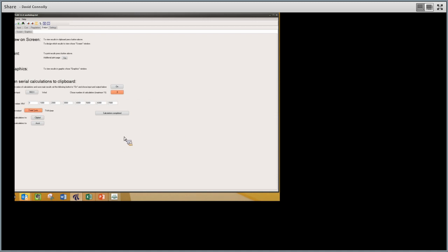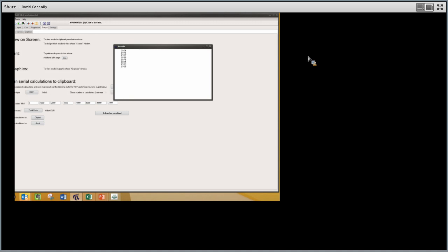I have to then tell EnergyPLAN what result do I want to see for all of these different inputs. So you can click on a variety of different options as the input that you'd like to see the result of. So I'll start by just looking at the total costs. So now what I've instructed EnergyPLAN to do is vary the input of wind power from 0 to 7,000 megawatts in these steps, and for each of those values, tell me what the total cost of my energy system will be. So I'm going to then click the preview results. And then I'll get the results you can see for each of the values.